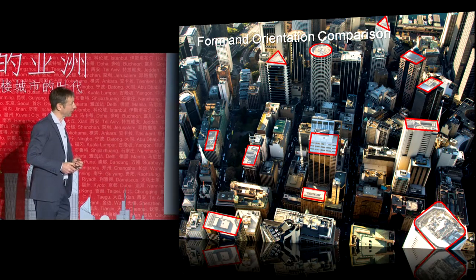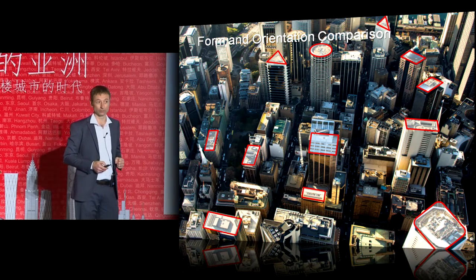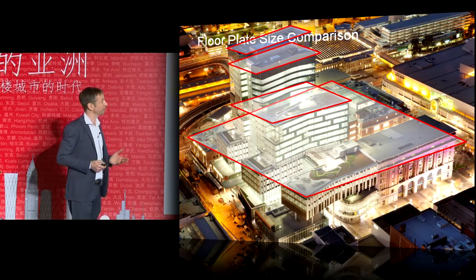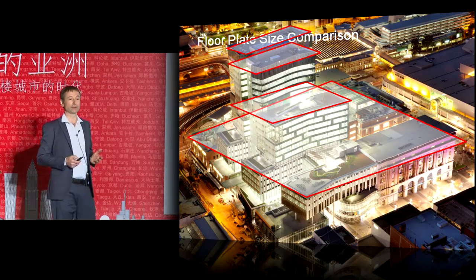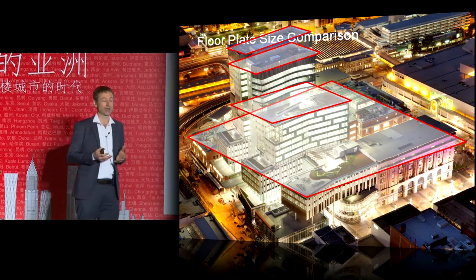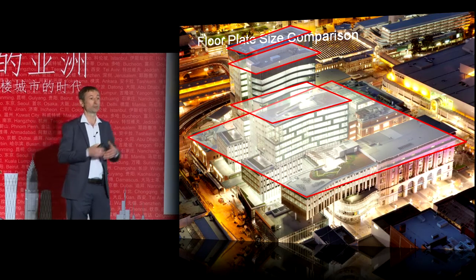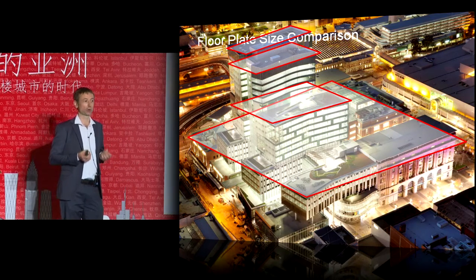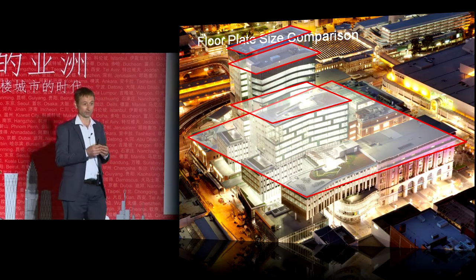But it's an interesting study in any case to see what influence any of those shapes will actually have on a building's performance. But of course, when you also look at the picture of a building which has got many different floor plates, if a building has got a facade on it, the larger the floor area, the smaller the percentage of the facade becomes. And so your facade will have a lower and lower impact on your building energy than you will for a smaller floor plate facade.